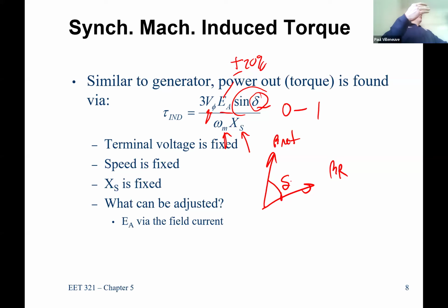But in that instant, the electrical motor will slow down just slightly to allow those two fields to separate. We don't often think about or talk about that in AC land because we talk about everything being in steady state. But in very short bursts, you do get movement of those magnetic fields as you try to put out more or less torque.